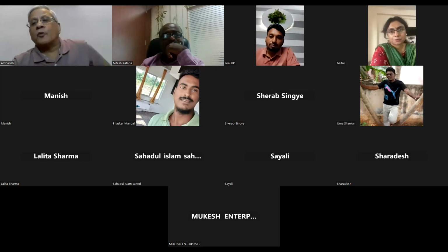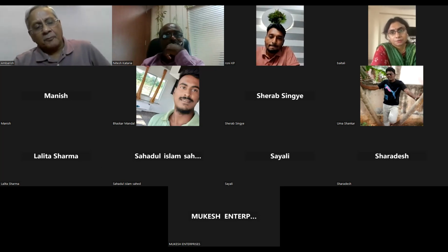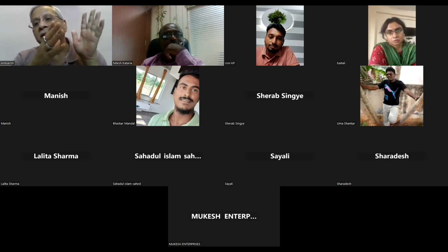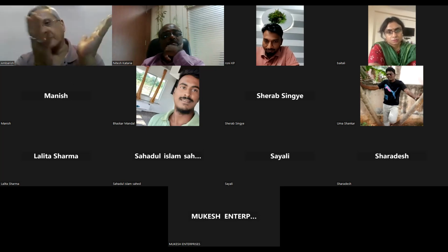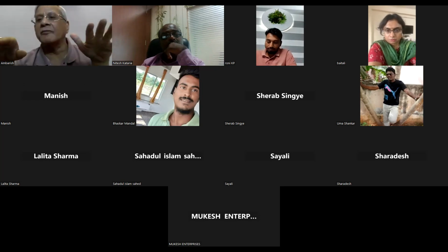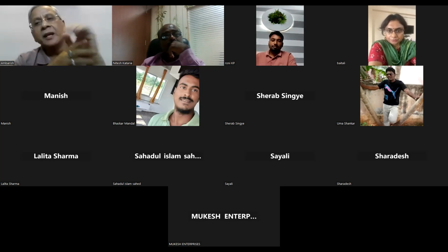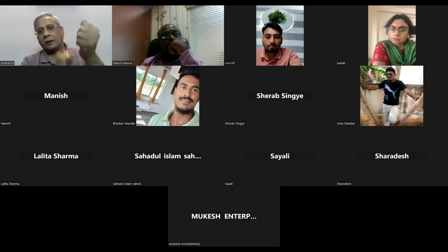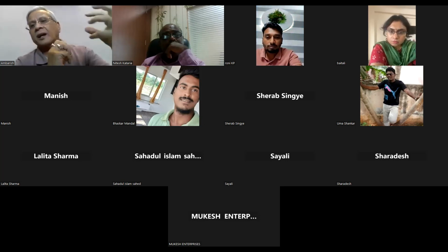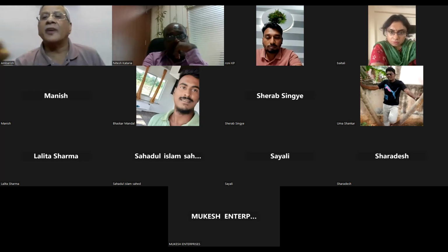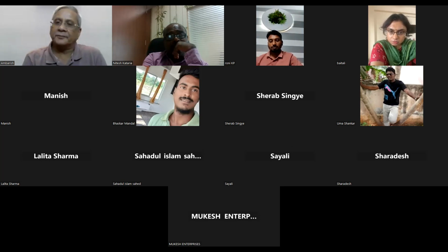So basically what Anup wants to say, Baitali, is with female connections which have got a flare, you have got flare and you've got inverted flare. A BSP has got an inverted flare, JIC has got a flare. In all flared connections, which he is calling regressive, you have to have a backup hex to tighten your hose assembly with the adapter. Otherwise, there can be a twist in the hose assembly, which is very detrimental for the life of the hose assembly.